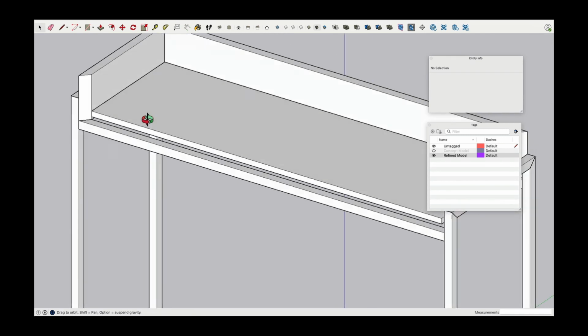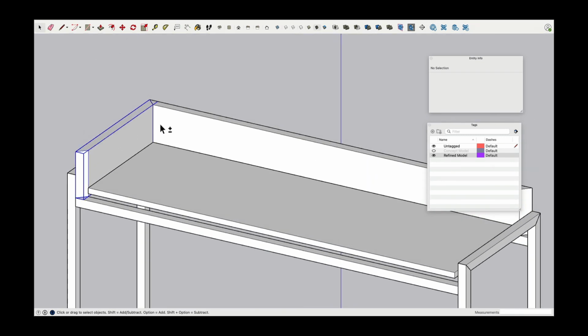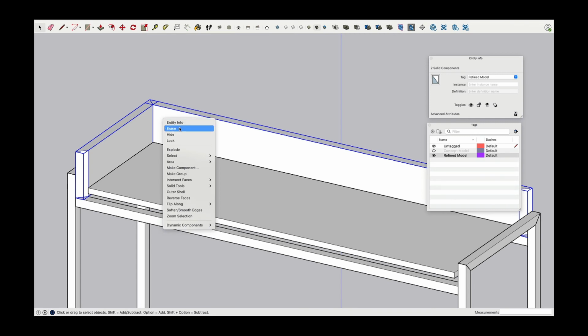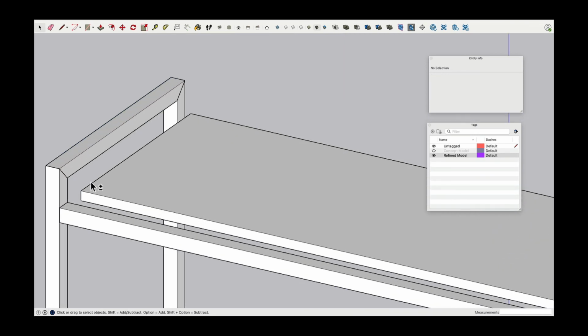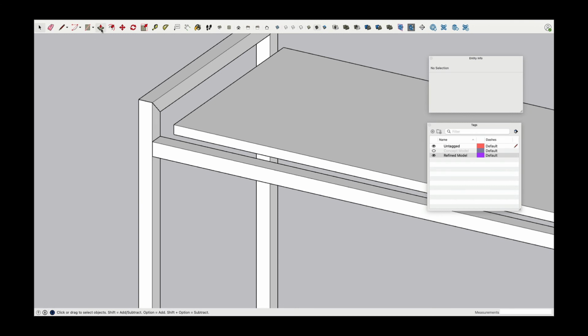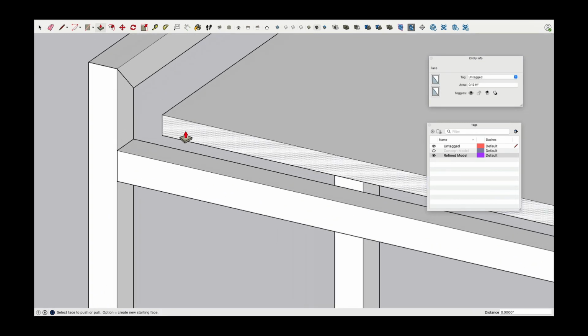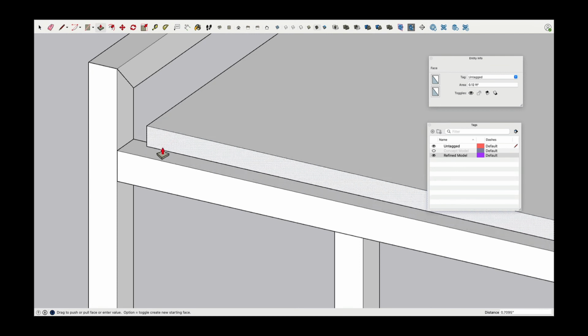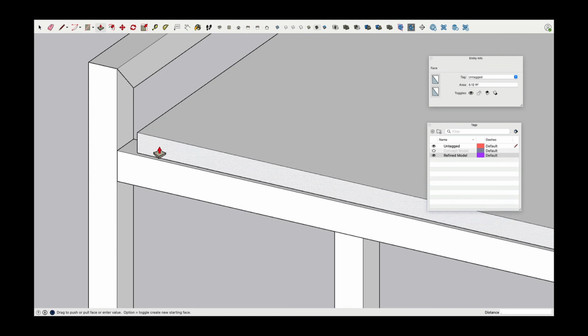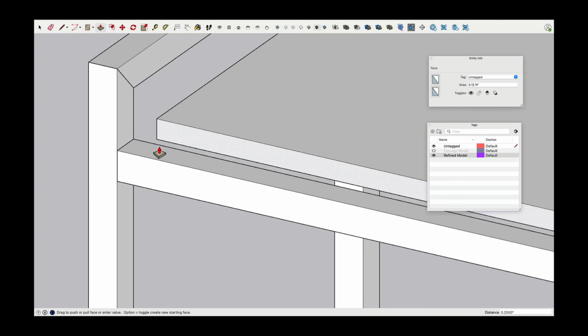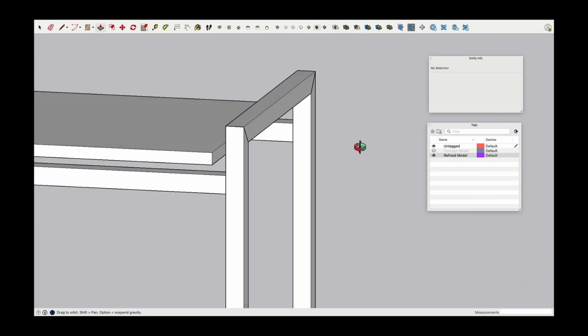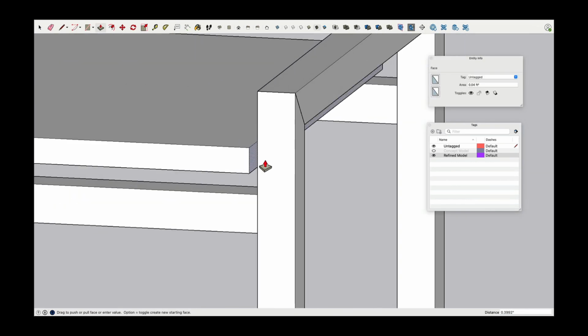Okay, very good. So I will show you something. So these two objects here, I will select, right click and say hide. And this needs to be expanded a little bit. So I go to the push and pull, click, move this a little bit so I can tell the software the direction, period 25, enter. Click, move, period 25, enter.